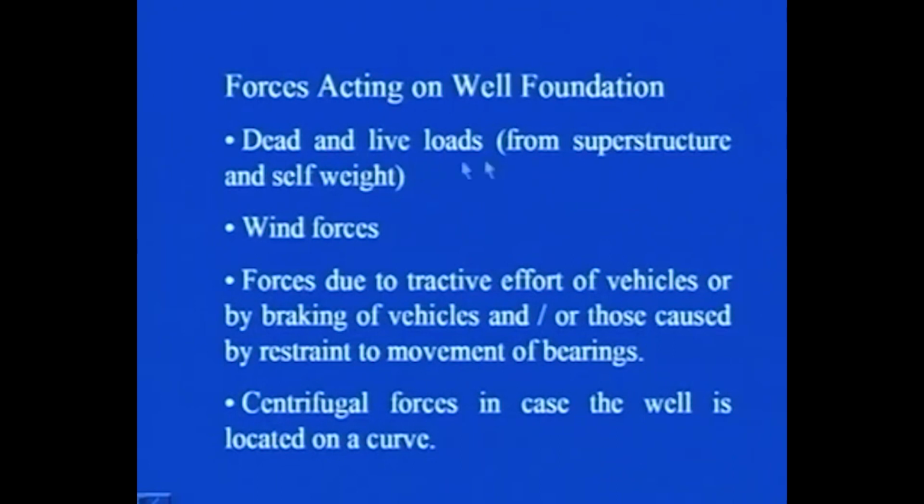What are they? These are dead and live loads which come from the superstructure and the self weight of the bridge. Then wind forces, because it is exposed to nature, and wherever wind forces are quite dominant, they come into the picture. Then forces due to tractive effort of vehicles or braking of vehicles, and those caused by restraint to movement of bearings.